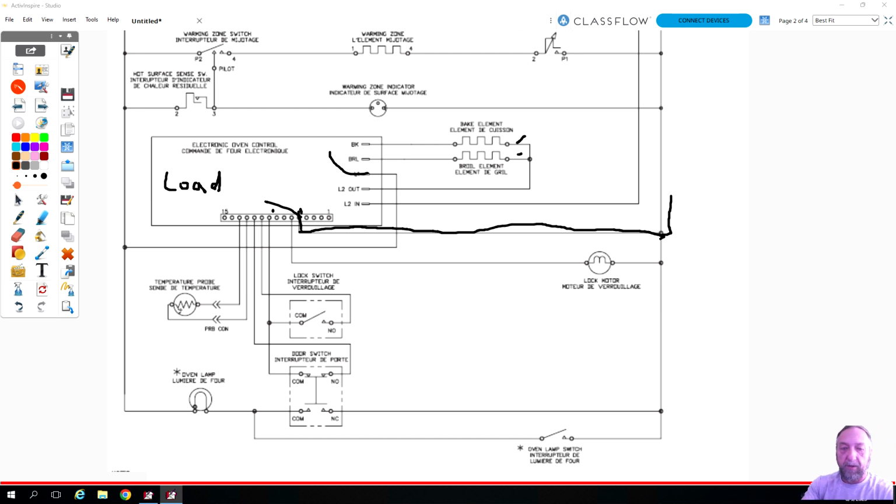I got a 120 volt test cord. I'm going to move the camera back a little bit so you guys can see what I'm doing. I got line 1 and neutral. I'm going to take line 1 and apply it right to this board here, to pin 5 on the board. Let me change it, I had one a little bit tighter. There we go, pin 5.